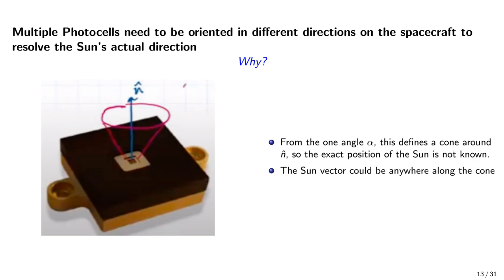So you have another one placed on your spacecraft, but while placing, you need to also put other things into consideration. And that is, you need these photocells to intersect, or overlap, so that you can actually have proper angles whereby you're measuring your direction from the sun.